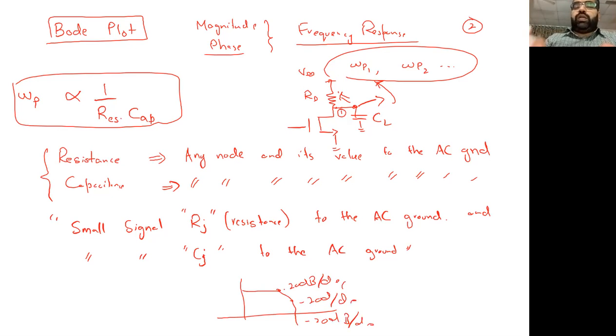So we can utilize a generic transfer function formula, which you might have seen in the last lecture or your feedback course, that H of s, any transfer function, is ultimately equivalent to the low frequency gain, or we can normally call it mid-band gain, or a DC gain, meaning you can write a mid-band gain as A naught,